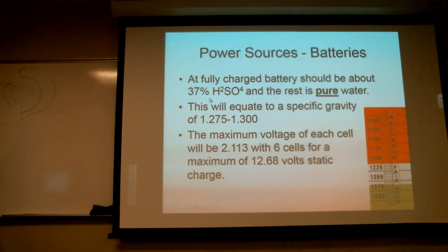Are you saying a battery can be overcharged as well? What overcharge looks like is you can't get any more sulfuric acid out of the plates. Okay. So you can't overcharge it there. What happens once it's fully charged is it continues heating and continues producing gas. So it starts turning the water into a gaseous state. Right. Yeah. Now that's why it gives off hydrogen and they blow up.